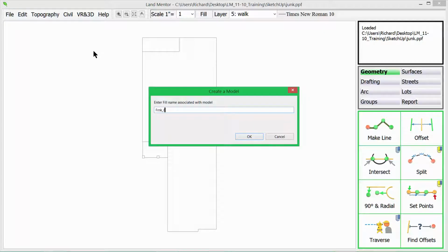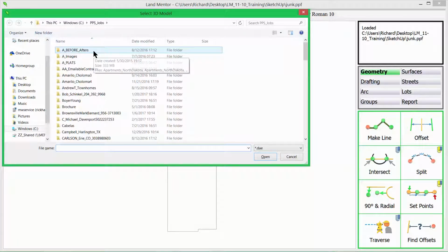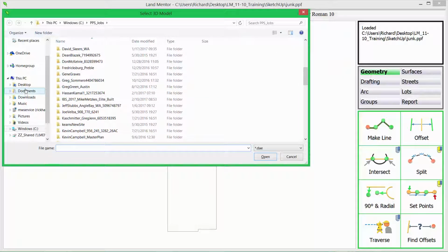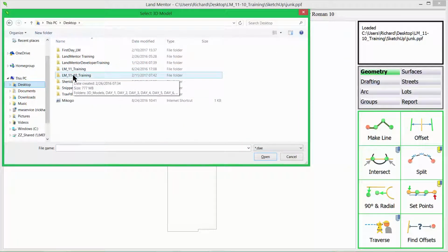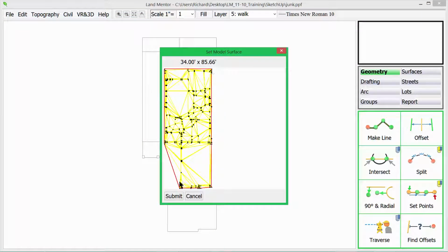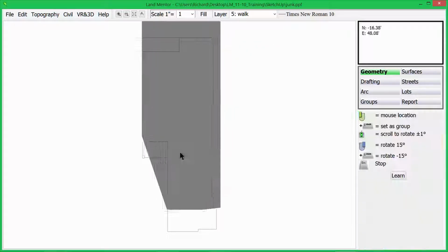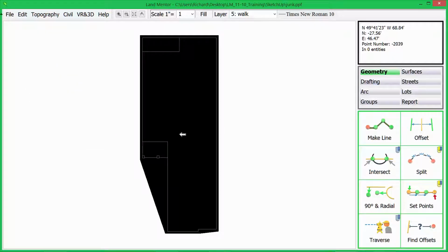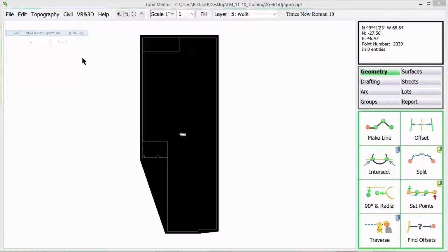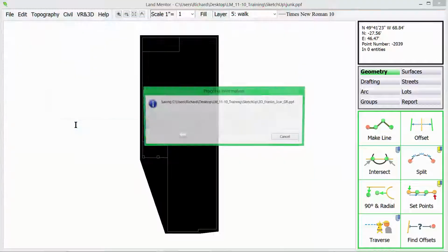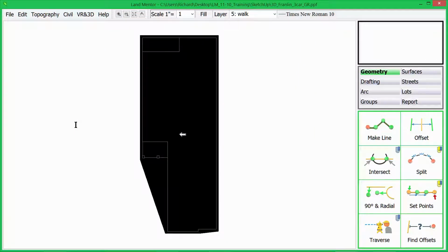and then a garage right, Frank R. So it's a unique name, something you haven't used before. It's very important because this software will look at the naming scheme and then call up that right side unit. And you're looking for the .dae file. That will come up now on the right side, submit, put it on the plan, and then hit OK, and then escape, file, save as, Franklin, and just turn the L to a right. Now you've got the 3D model saved.